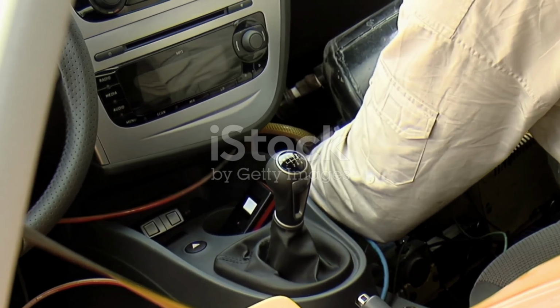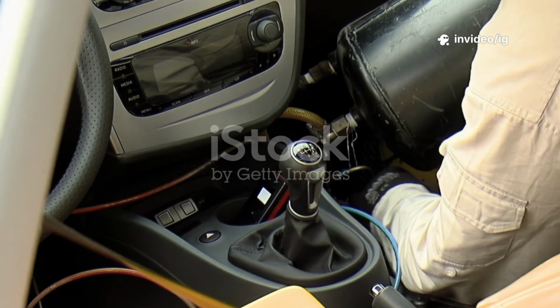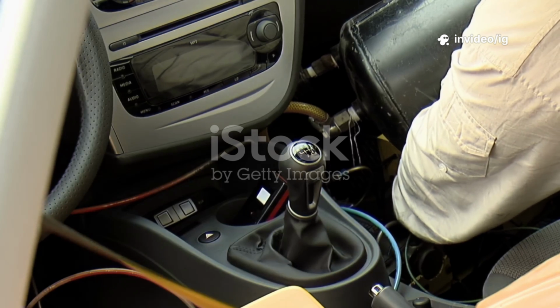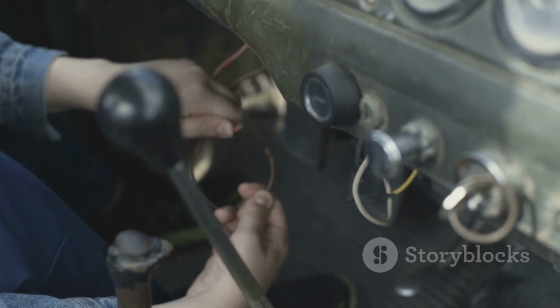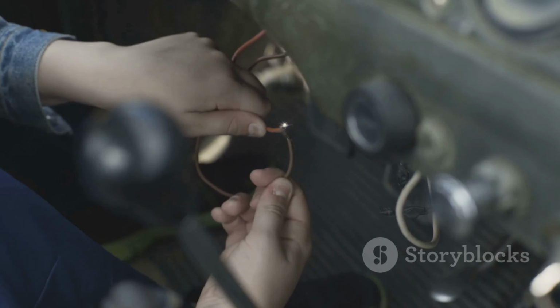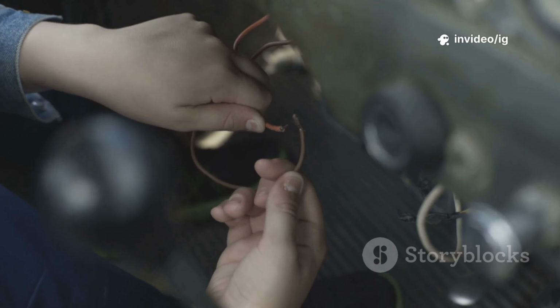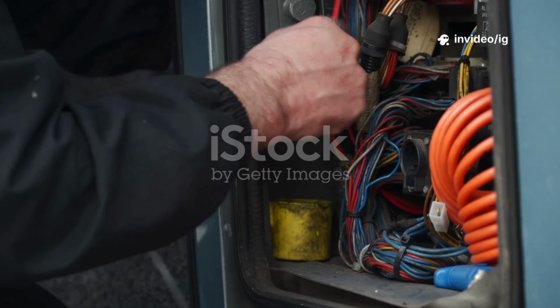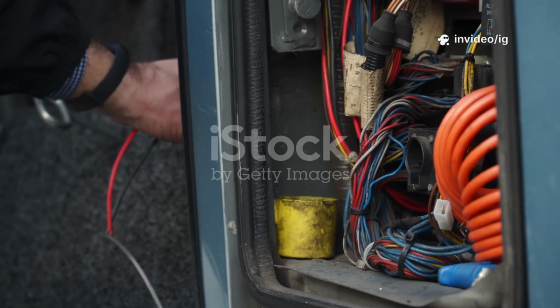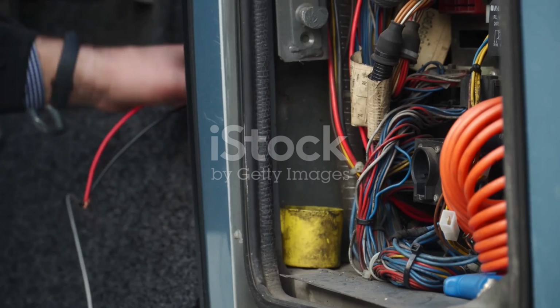Common causes of P0815: faulty upshift switch. If the button or paddle shifter is broken, the transmission won't receive upshift commands. Malfunctioning gear shift lever assembly. Some models have the upshift switch inside the gear shifter, which can fail over time. Damaged wiring or connectors. Corrosion or loose wiring between the switch and TCM can cause an input failure. Failed transmission control module. If the TCM doesn't process the signal correctly, the car may not shift gears.